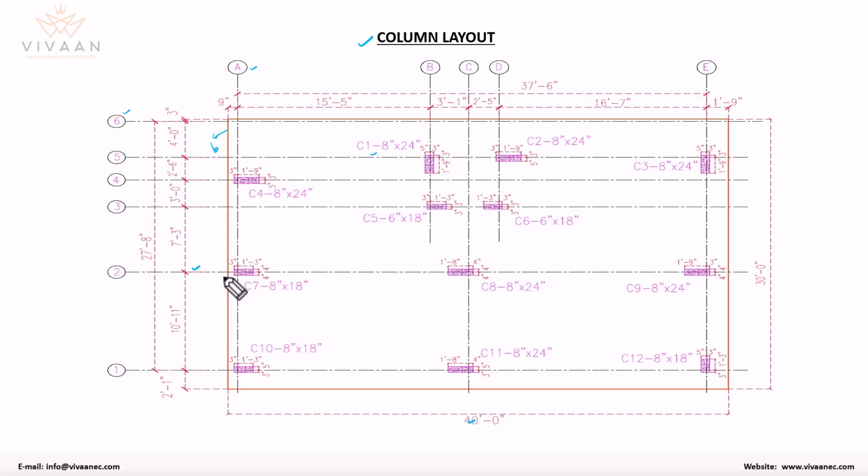While we design the building, we need to consider the dead load, the live load, and the wind loads for the location where we are constructing the building, and also the earthquake zone where the building is. And if you are in a snowfall area, we also need to consider the snow loads. I have seen that most of the time, designers are neglecting the wind and earthquake loads.